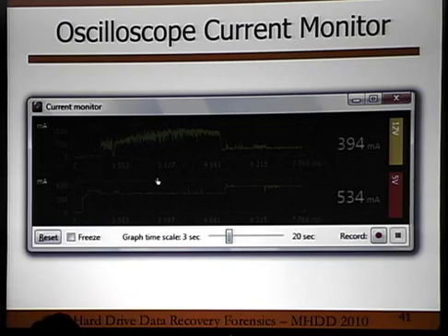In this particular case, I can tell this is a 3.5-inch hard drive because I have 12 and 5 volts. If I have a laptop drive, I'm only going to have 5 volts. So there are certain things like that where you can use an oscilloscope if you want to graduate through the electronics components. I can also tell if a processor is in use. You can see when the processor utilization goes up based upon it reading a sector and getting stuck in that pattern.